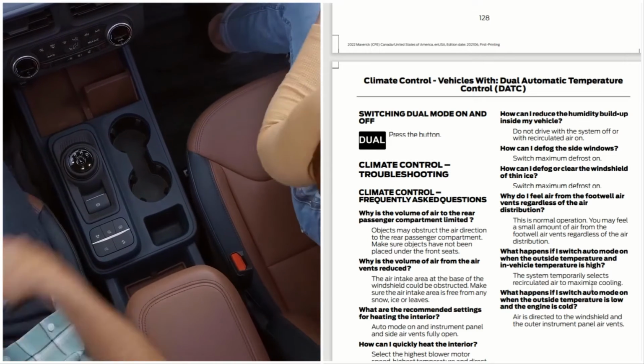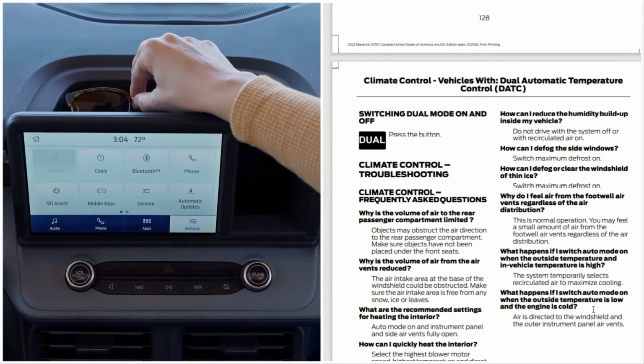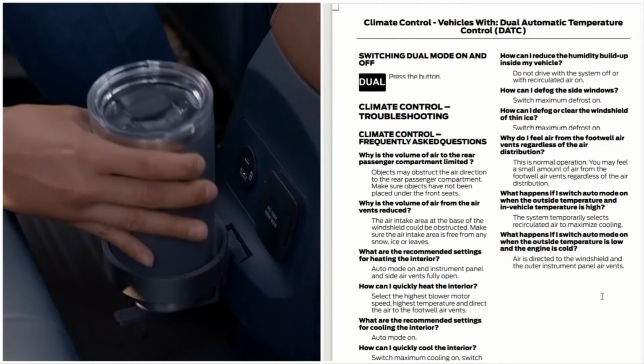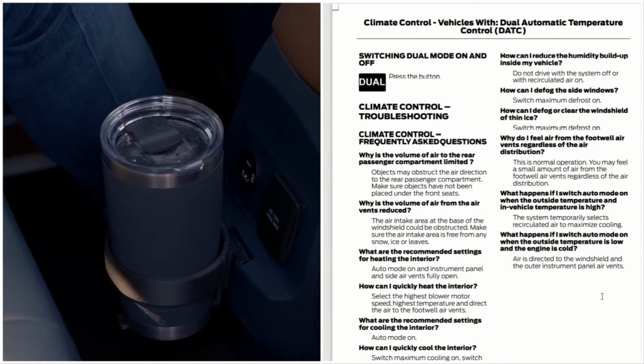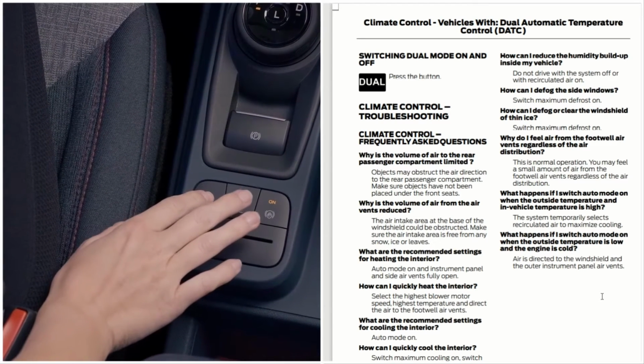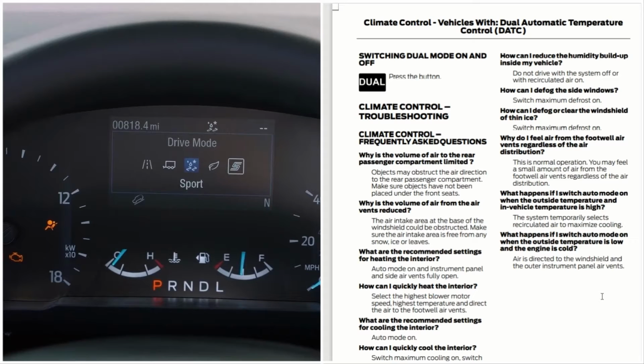What happens if I switch auto mode on when the outside temperature and the in-vehicle temperature are high? The system temporarily selects recirculated air to maximize cooling. What happens if I switch the auto mode on when the outside temperature is low and the engine is cold? Air is directed to the windshield and the outer instrument panel air vents.